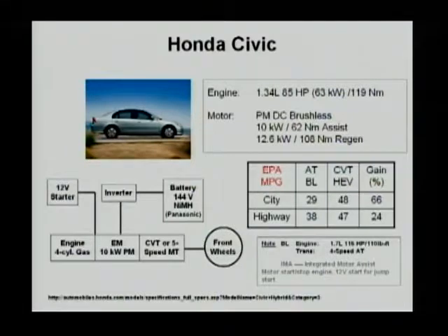And you can see that in this system design, even though the newer model has a 15 kilowatts motor, that motor is usually rather small to drive the vehicle alone. So if you happen to have the chance to drive a Civic hybrid, you will see that the engine will start very frequently, even at very low vehicle speed. So I would say that this type of vehicle, because the motor size is limited, cannot be used as a plug-in hybrid, because you will not be able to take advantage of onboard electrical energy.